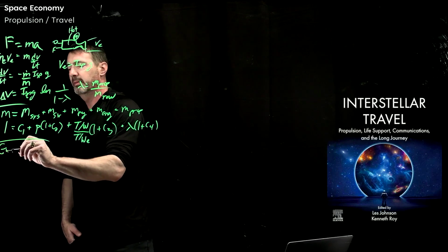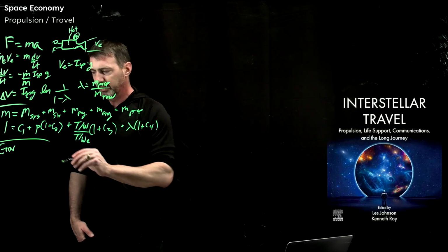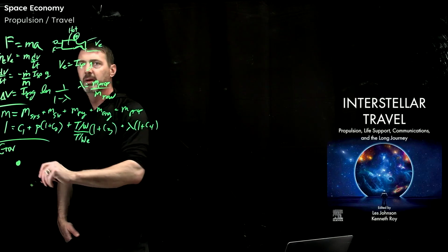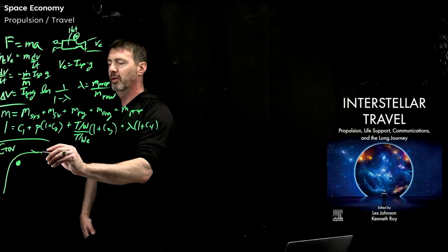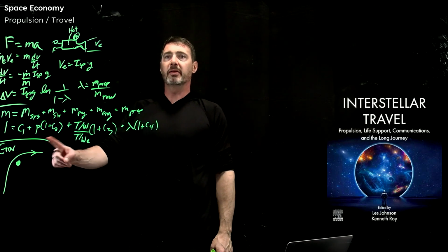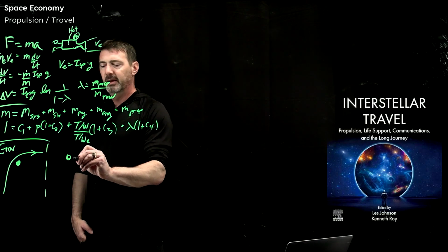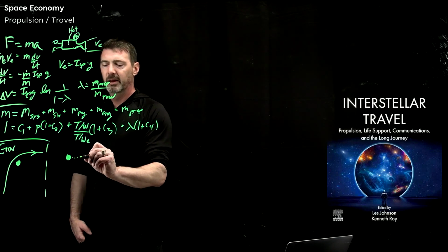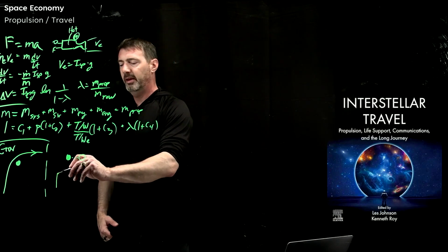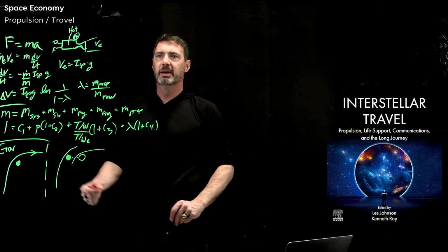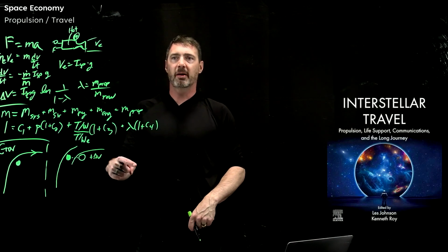Okay, gravity assist. And what's happening there? So imagine you have some sort of planet, and from the planet's point of view, here comes your satellite or your probe or your vehicle, and it just bends around. Okay, well, that's from the planet's point of view. What's actually happening, though, is the planet is starting here, and I'm going to exaggerate, and it's going to move to here because it's orbiting the sun. And so as I start this, ultimately, you can see I'm actually getting drug along. And so I actually get this kick. I get a plus delta V kick if I do it that way.